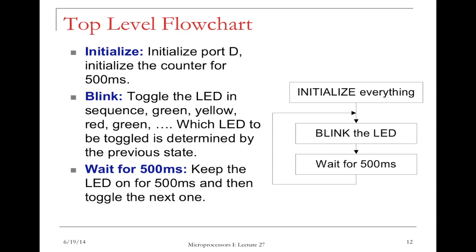We start with high-level thinking. We want to have a top-level flowchart, which will guide us to the design of this program. We will need to initialize port D and initialize the counter for getting this 500 milliseconds. Now, here we have two parts. Initialize port D. What do we mean by that? So port D is the I/O we use to control these LEDs. And let's say for any single LED, one connection is to the pin of the PIC microcontroller. The other end of the LED is grounded.